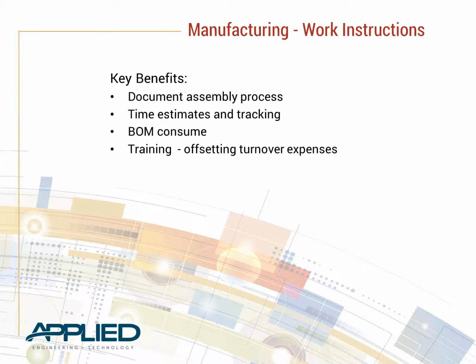Say in the assembly process, when you're doing work instructions, if your BOM or your model is already made in sub-assemblies and assemblies that are conducive to how you'd actually build it out on the floor, well, all of a sudden the documentation process for assembly just got a lot easier because everything's in the right assembly. Then you can start to break it down again by workstation, operations, and then also do that for the bill of material consumed, so you have work instructions the whole way through.